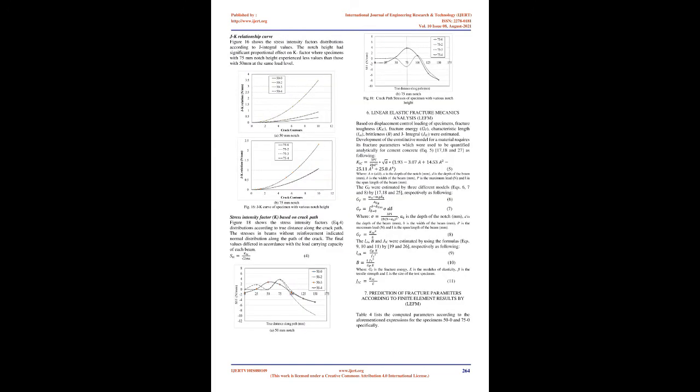The two supports were modeled as hinged and roller supports. The relation between the concrete and the steel reinforcement was assumed to have full bond and was modeled by the embedded region constraint. Validation of analytical finite element results. Comparison between numerical analysis and experimental results. Table 3 summarizes the maximum flexure force, corresponding vertical deflection for experimental results and maximum concrete and midspan steel strain, experimental and finite element results, which were extracted from the Abaqus finite element analysis.